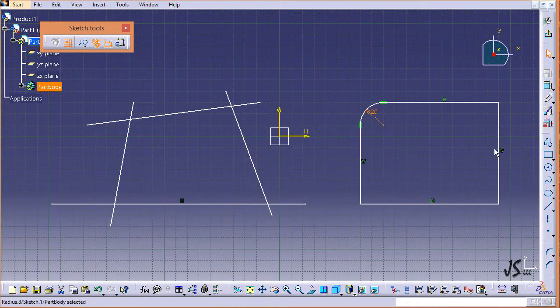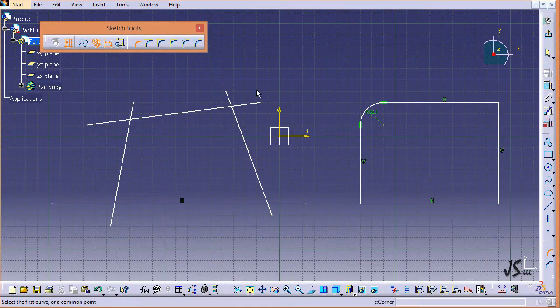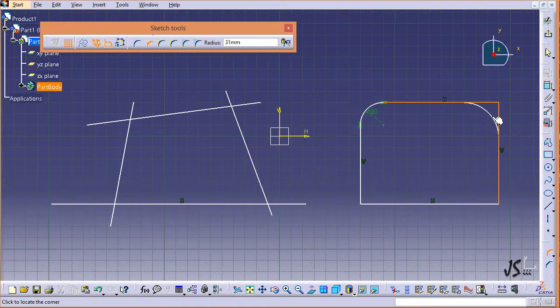I'm going to select this command one more time, and this time you can see that I'm going to select the first element to be trimmed. So I click on that, and this means that when I am clicking on this line first, the extra part of this is going to be trimmed, but the second line is not. So I'm going to select this one first and select this one second, and you see this here.